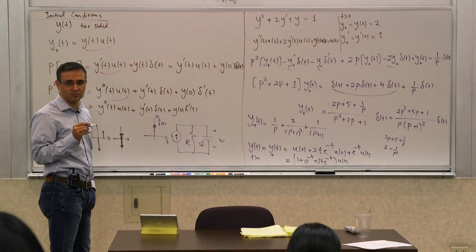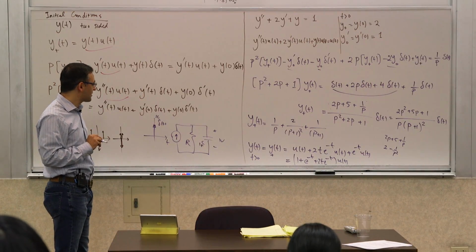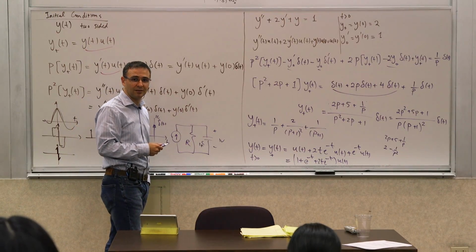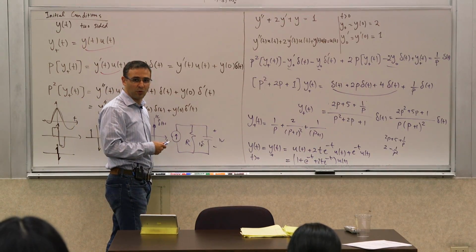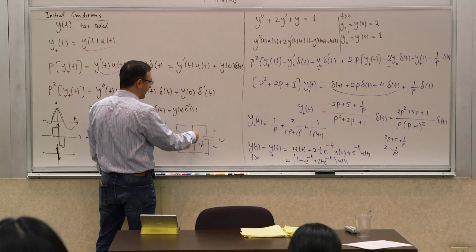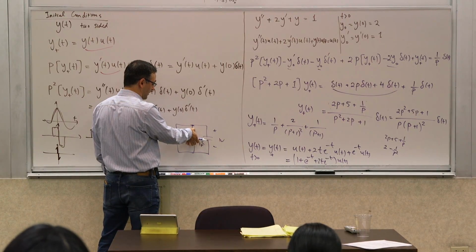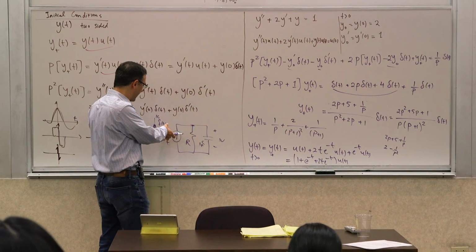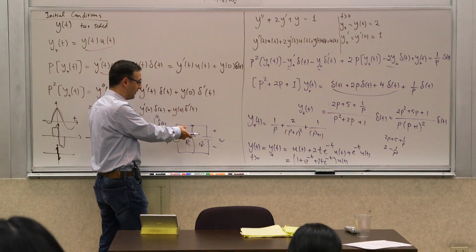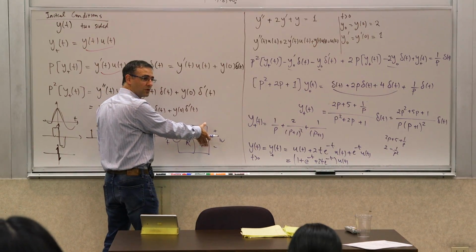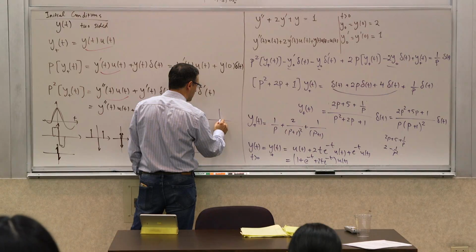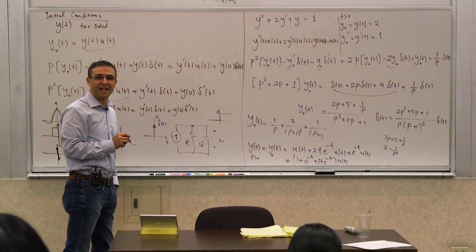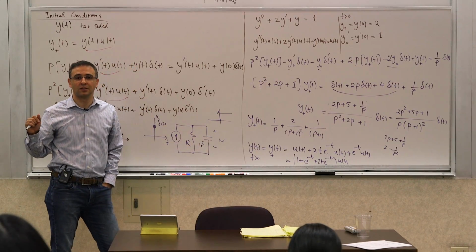well, an area of 1 coulomb more accurately, what happens? That impulse, that current, will go through where? The capacitor or the resistor? It will go through the capacitor, right? Because if it goes through the resistor, its voltage will instantaneously go to infinity, because at that point you have infinite current. But if it goes through the capacitor, it just raises its voltage. So instantaneously, it shifts its voltage from 0 to 1 volt. So it's as if I've set it up with a 1 volt initial condition.